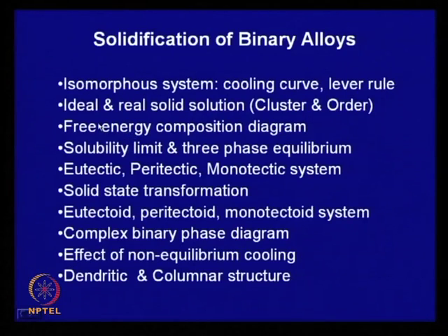Then we will make a distinction, look at what kind of material, say, what is an ideal and what is a real solid solution. We have introduced a concept of free energy, which defines the stability of phase. We will see how the stability of phase changes with composition. Then we will look at the solubility limit and 3 phase equilibrium, and under this some of the common 3 phase equilibrium we will take up are eutectic, peritectic, monotectic system.